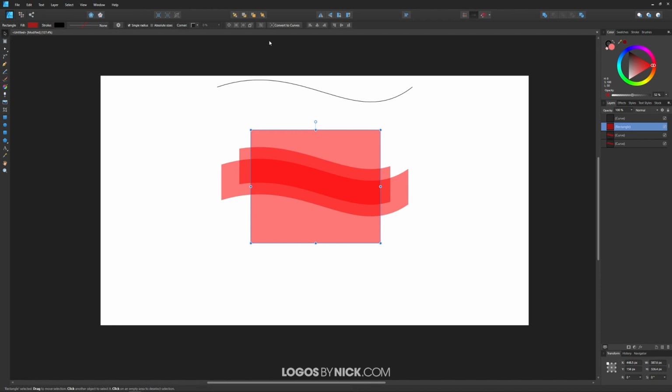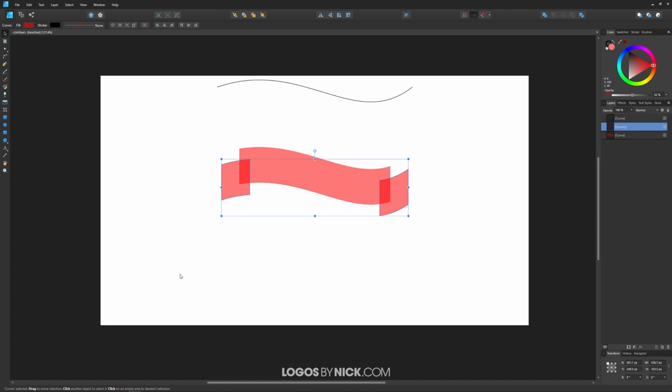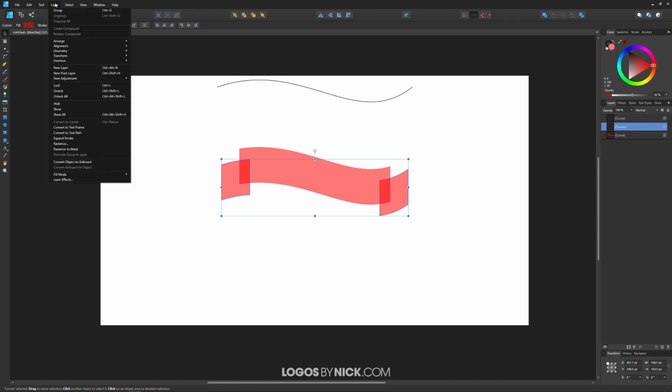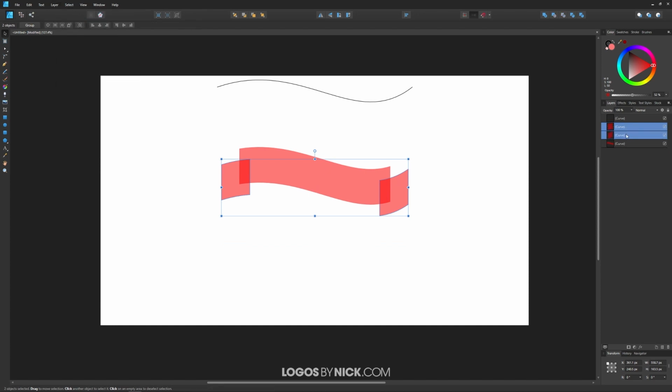Let me grab the select tool and just make sure I have this aligned on the vertical axis like that. And then hold Shift and click on this larger shape right here. And we want to subtract. Click on this button that says subtract. And there you go, you get something like that. Now let's break this up into 2 individual parts. To do that, once again, we'll go to Layer, Geometry, and Divide. And now that's 2 separate objects, as you can see indicated in the Layers menu here. So let me click off of this to deselect everything.